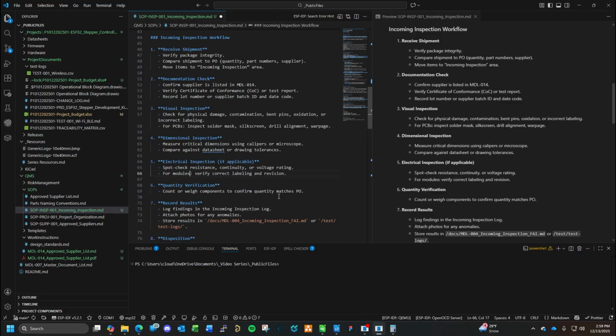Because it is extremely possible to have a via plug in wrong and actually tie a ground plane to a power plane. And yes, I've seen that before. It was by an older engineer who did things backwards. For some odd reason, this engineer would lay out the PCB first, and then capture the schematics, run them as separate processes, and not use the tools that exist, such as design rule checks and electrical checks that are built in to make sure the nets aren't shorting out.